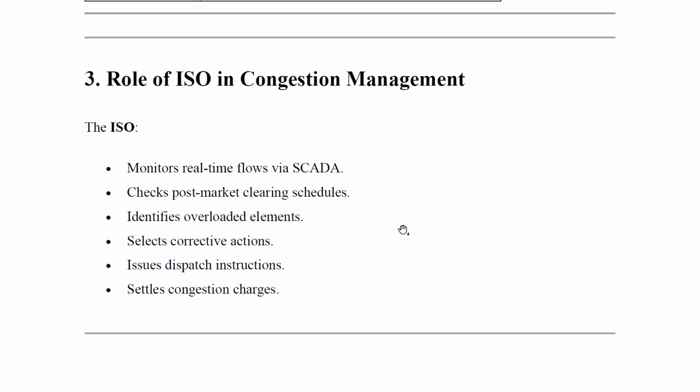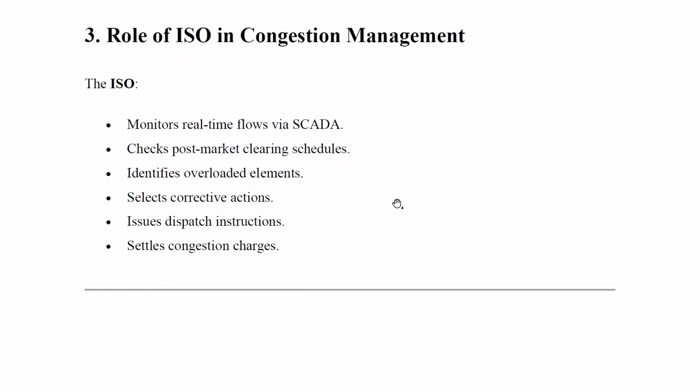Next, what is the role of ISOs in congestion management? The ISO monitors the real-time flows via SCADA, that means supervisory control and data acquisition system. So it will always monitor the real-time power flows. It checks the post-market clearing schedule, for example, whether they are following the scheduled power only or not. That also the ISO has to check.